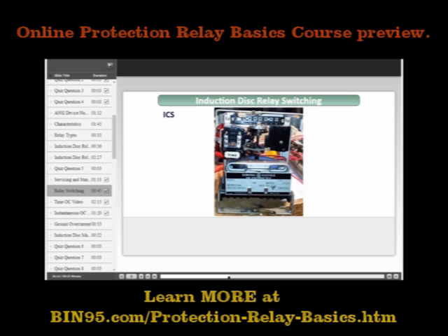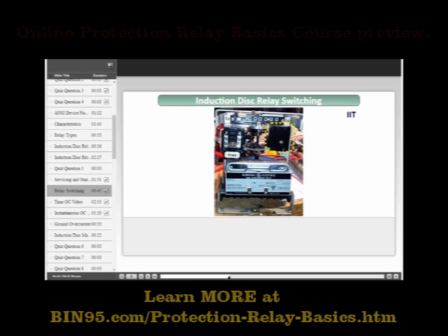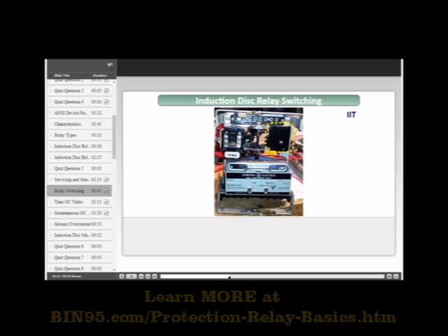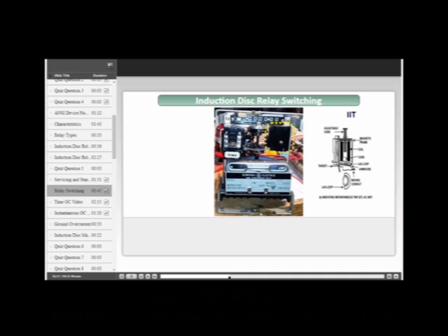The IIT unit seen here operates as an instantaneous overcurrent or as an instantaneous trip unit. Its adjustable core provides pickup adjustment over a nominal 4-to-1 range. It consists of an adjustable core as mentioned, coil, core, lag loop, armature, moving contact, and target indicator.